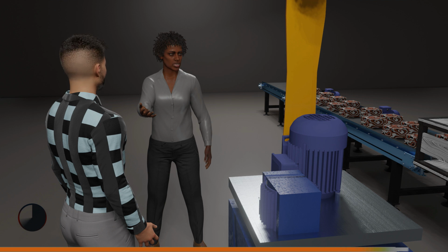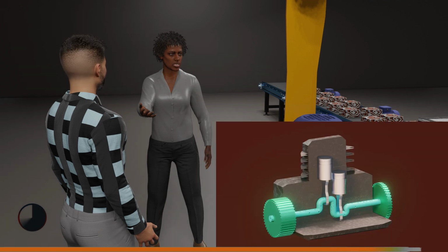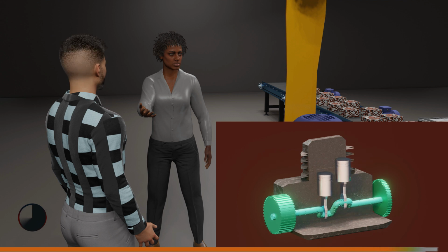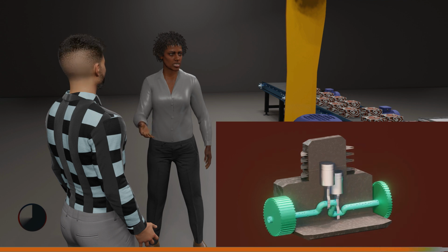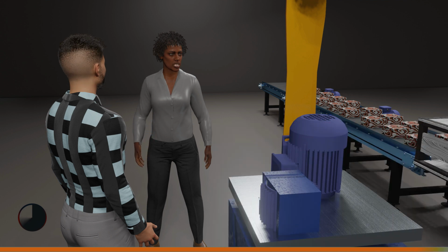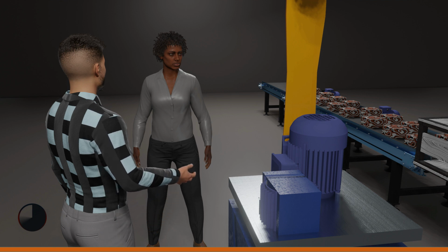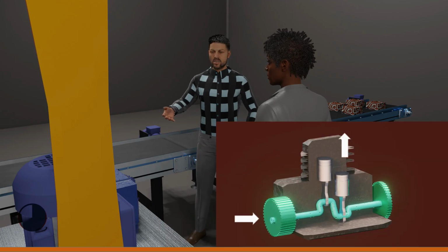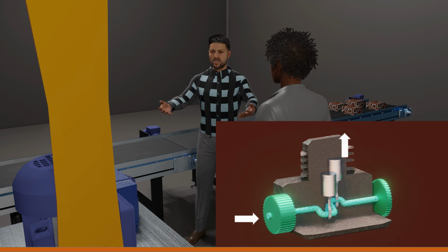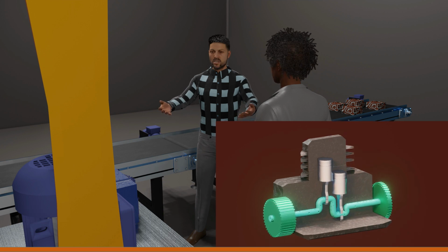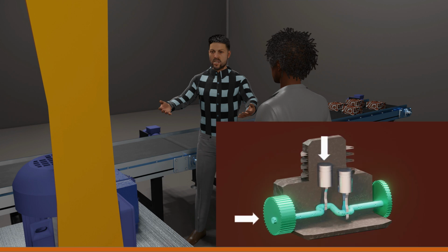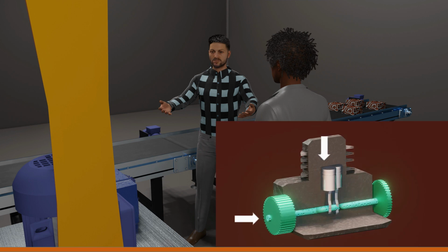Now, it can be said that the piston moves in a reciprocating motion, while the crankshaft through the connecting rod moves in a circular, or rotary motion. To further make it sink in, when we turn the rotating end by hand, reciprocating motion will be generated. However, when the piston is pushed downward, a rotary motion will be generated.